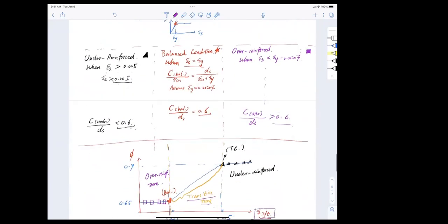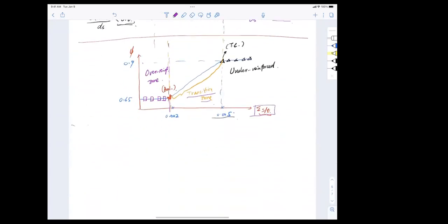But to finish the calculation, keep eyes on the ball, right? What are we looking after here? We are looking after the calculated design moment. That is Mn, nominal. Again, let me write it down. So nominal moment resistance, or nominal flexure strength, whatever you call it. So that, ladies and gentlemen, has to equal the tension force multiplied by the lever arm jd. Or if you hate to use tension force for some reason, you can always use compression force as well, use jd, but nevertheless, let's use that.